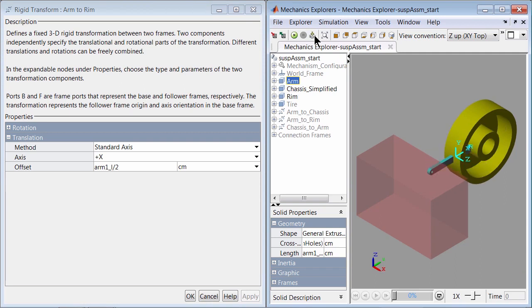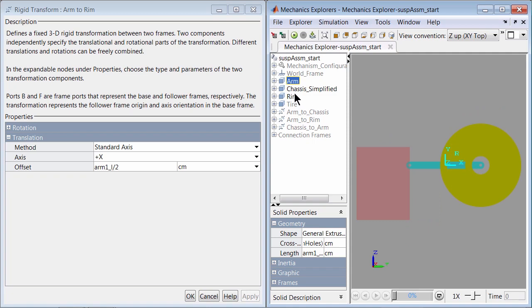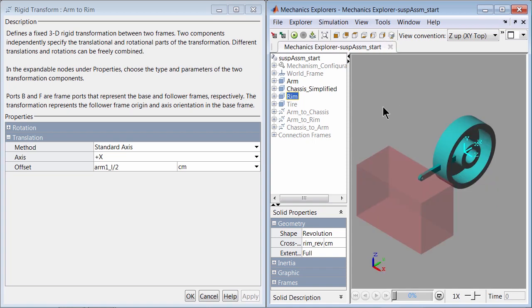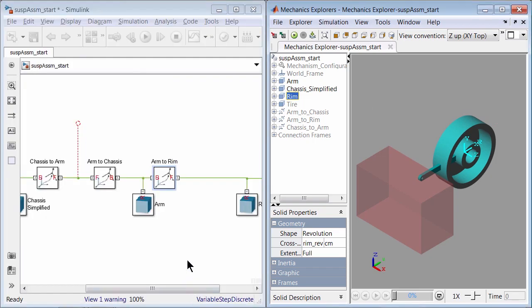the arm. We can switch to the right view and take a look at the rim coordinate system to see that it is at the end of the arm. Let's go back to the isometric view. Next, we need to rotate the rim with respect to the y-axis of the rim by 90 degrees. So let's select OK to save changes here.